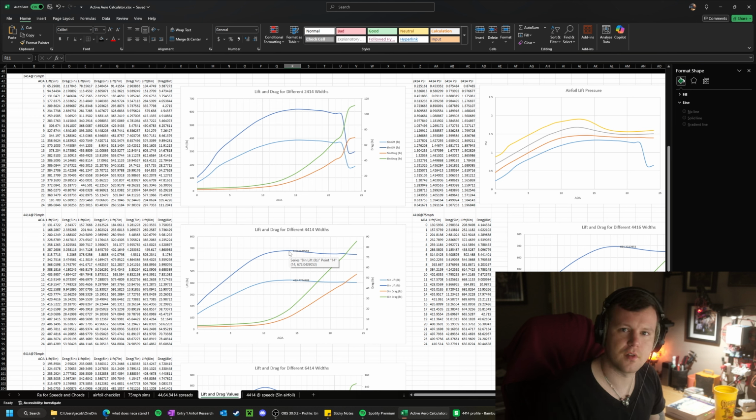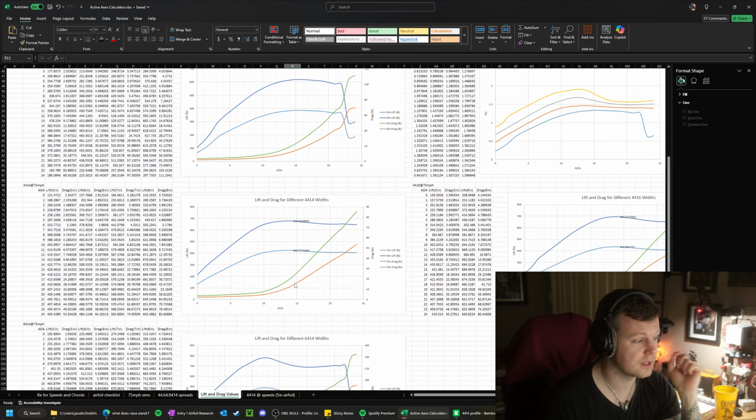Anyway, if your downforce drops off, you could spin out easily because you're at the limit, and then you're trying to brake, and the active aero is trying to help you brake, and then your downforce drops off. It's just a bad time. Now we can correct for that in software and the control system, where it's like, okay, don't go beyond a certain angle of attack or your lift's going to drop off. But if we can have an airfoil that can assist us in braking as well, that could be really handy. And if we want to maintain lift and increase drag in a high braking, high G turn, that could be really handy.